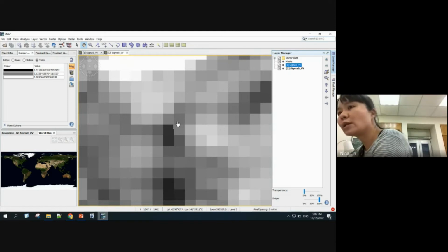When it is doing the terrain correction, equivalent to geocoding, it's trying to geocode based on the AOI that you appointed, not based on the exact boundary of the SRTM 1 second grid. So that's why you will always see a misalignment between the images. Also, your images are acquired at different paths, with a different range and pixel location on the ground.